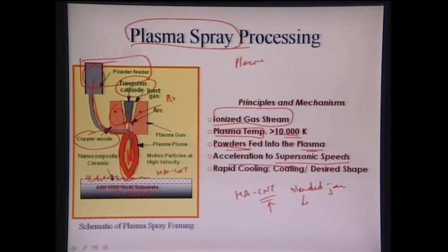It's more like playing with water balloons. So we are taking a water balloon and then we are impacting it onto a surface. So there is a kind of layer by layer deposition which really occurs via this particular processing. So we have a powder particle, it is accelerated because of the carrier gas, and it passes through the plasma, the surface gets melted and the particle becomes molten or semi-molten in nature. Then once it is impacting the substrate, it forms a splat, and then successively other molten or semi-molten particles impact onto the substrate, and from that we develop a coating.